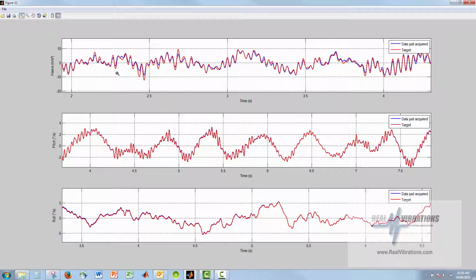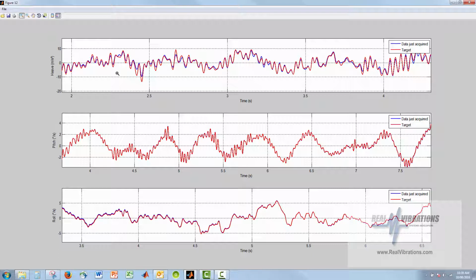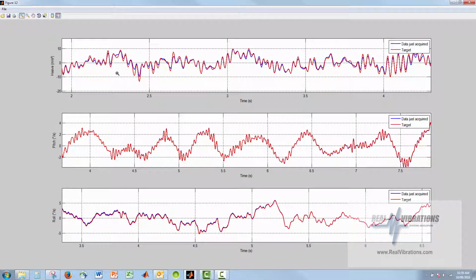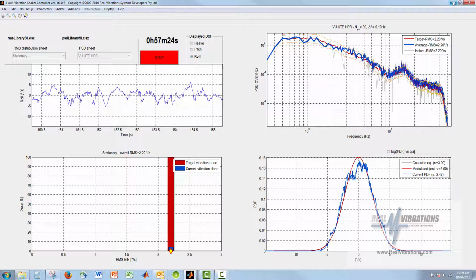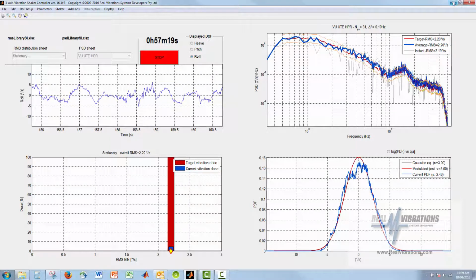Our work has shown that the 3 quantities, heave, pitch and roll, are in the time domain essentially uncorrelated. But in amplitude domain they are correlated. But this only comes into play when we use variable RMS or non-stationary simulation. For stationary simulations, which are essentially an artificial case, the RMS levels are simply selected based on measurement or other arguments, and the system simply works as it does.